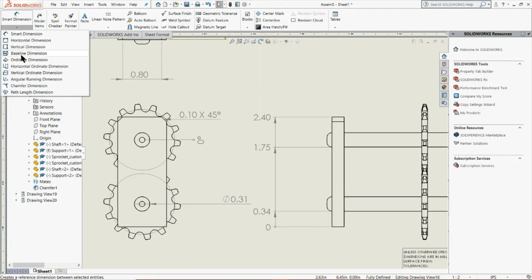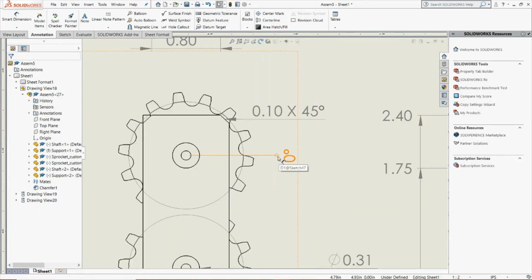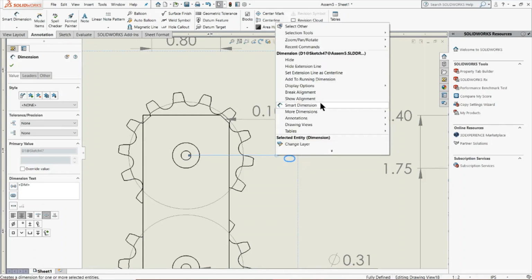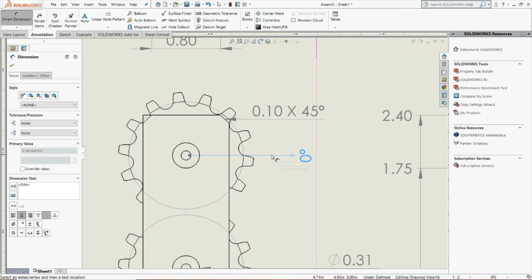Now, I intentionally skipped the angular running dimension tool. And that's mostly because of the fact that I don't necessarily have a model on hand right now that this would work well for. But think of it like so. Say we have this dimension here, so this was from before. I'm going to delete this guy and apply a new angular running dimension. And click on this circle and apply a reference.